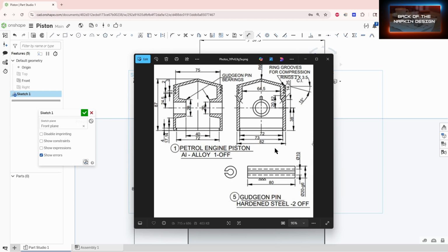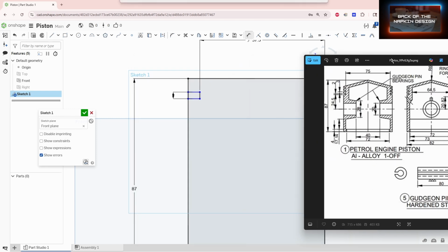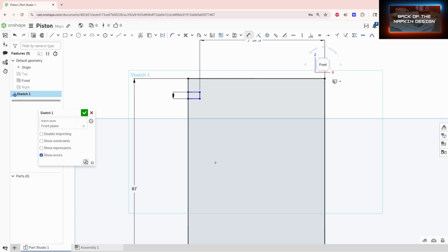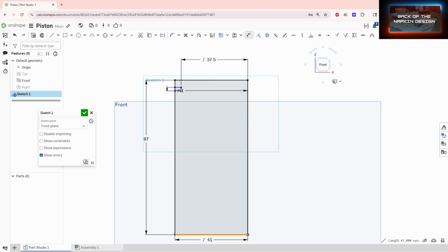On the drawing of the piston, I show from the bottom of the piston all the way up to the center where the rod goes through. It's 38. So it's going to be 38 plus the 24.5 to get us to the lowest area. So let's do that. We can do the math there. Click all the way here, and we're going to click on that. We're going to put in that number. The first number was 38 plus 24.5. Okay, and that's our first piston ring.